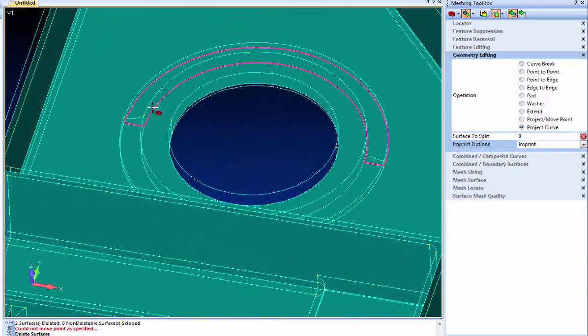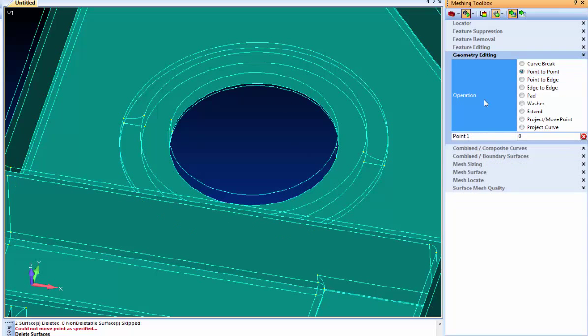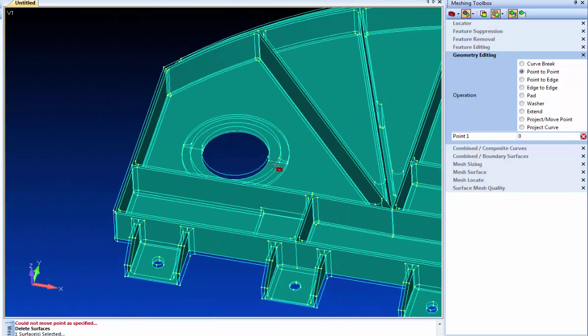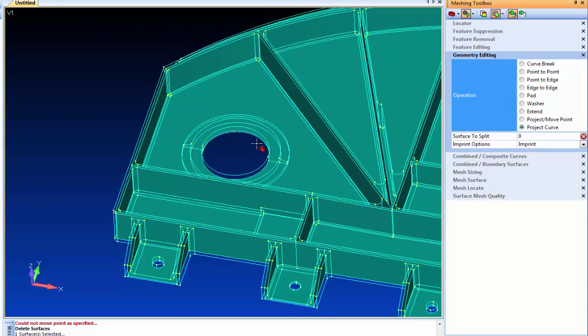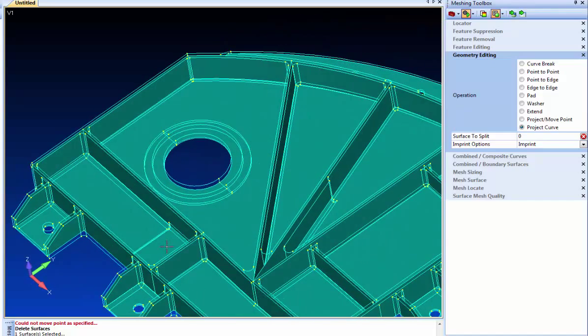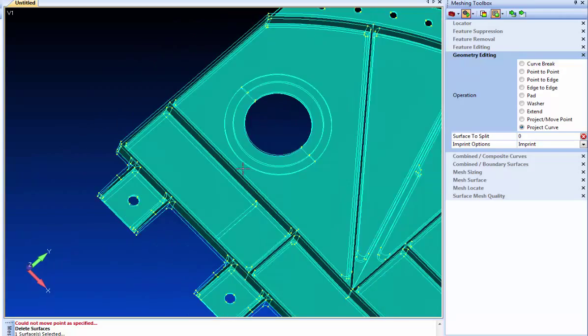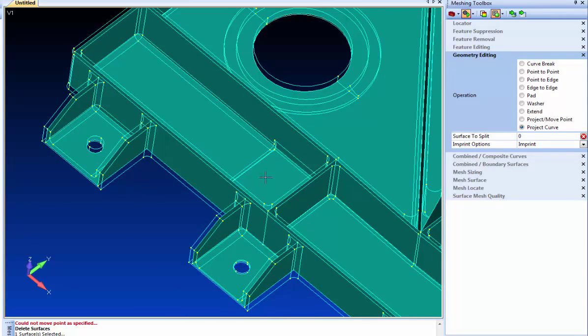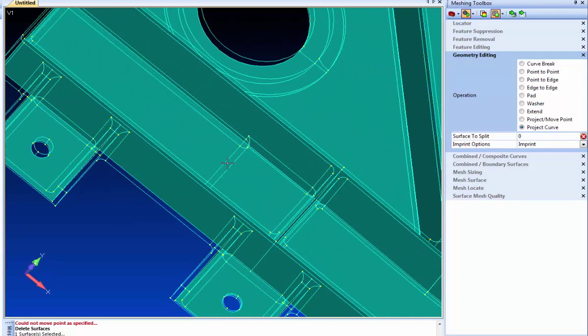And then when I really want to get into some mapped meshing, instead of having this circular annulus here, I'm going to use another split option we have in Femap and just split down in here. So now I'm going to be able to just play with the meshes later on. Now one other thing we need to do on this part, there are a couple of regions where there's thicker regions in these pockets that I definitely want to capture. So I need to kind of burn those splits in too into the mid surface.